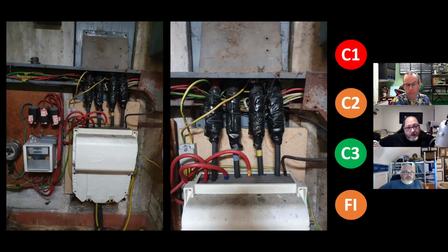On that one, in my view, yes, there's some lash-ups with the cables and the trunking. That's a separate observation. Those are C2s. But there's an FI with regards to identifying the earthing system on this one. Yeah, for me. And the joints are a C2 code. I think we're all agreed it's just poor. And if that's an approved DNO method, then the DNO seriously need to consider what approved is, because that's just pants.